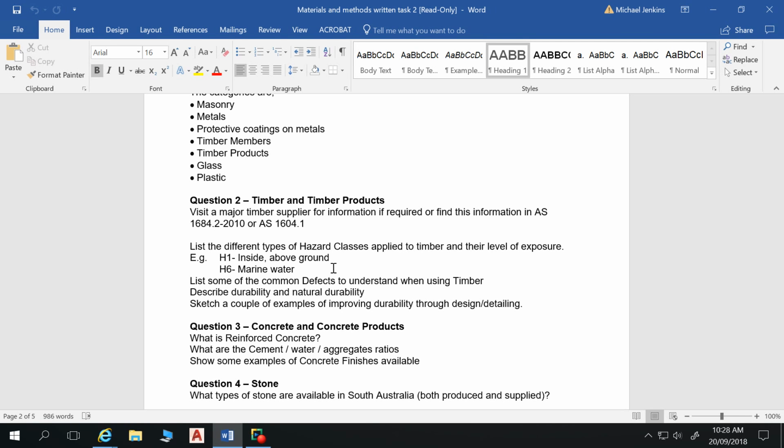So this end bit is a little bit more protected from the weather than that end bit there. That's a very common detail to help preserve the ends of our rafters. Basically it's chopping off the end of the rafter that would start to dry rot and then harbour moisture and then rot the rest. But there are a whole bunch more details. So think about those details, the things that help keep timber durable.